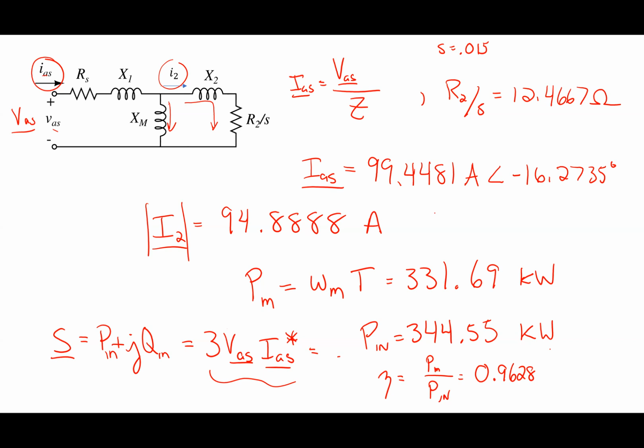That is to say that the mechanical power is basically everything going into rotation. So it would be the friction in the bearings and the friction from what we call windage as this guy spins. The shaft power is what's actually getting transferred to whatever pump or fan is connected to this thing. All right, so there are a little bit of losses that I'm not adding in here. Questions on that?